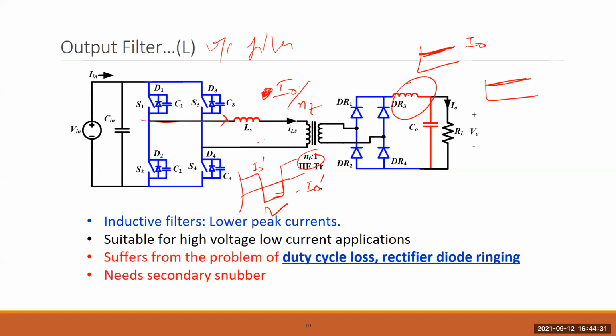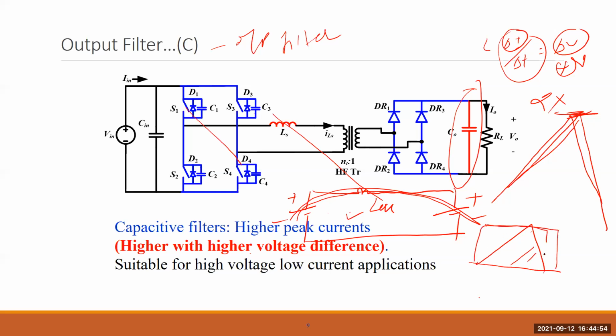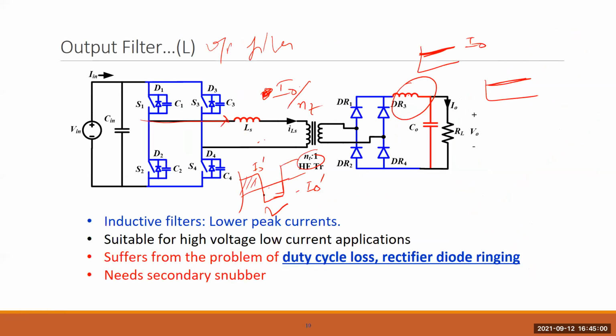Okay, current limiting. And here it is basically two voltage sources, and based on the switching, the voltage difference appears and current rises and current falls like a triangle waveform. And so this peak current is 2 times, because in a triangle the area under the curve is half of the full one, right? And here it is basically already a square wave. But if you have a triangle wave, then this area is half. So this peak should be double for the same power or the same current.